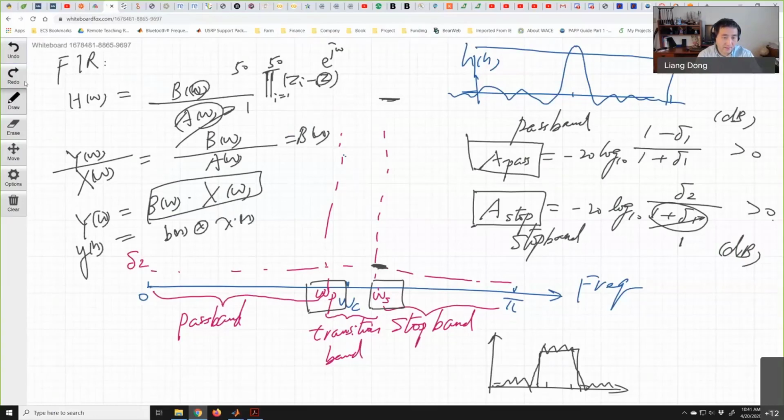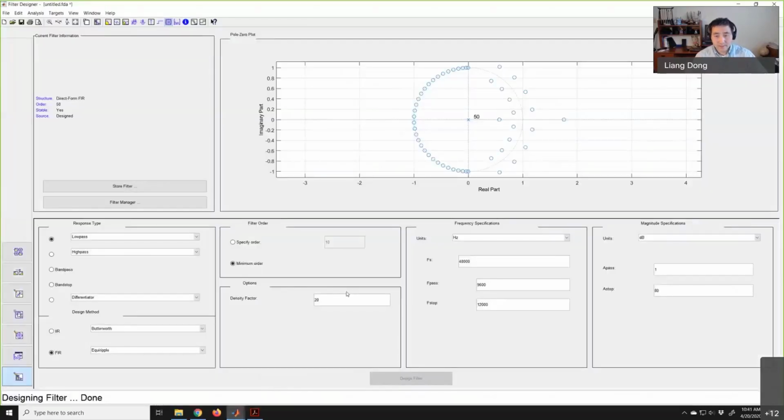Right? This is actually my h here. That is a finite impulse response function. I convolve with a finite number of those non-zero h[n]. I don't have feedback. I don't have this term. This term is 0. So we have no poles in this case. All the poles are deformed onto the origin. That makes sense here.